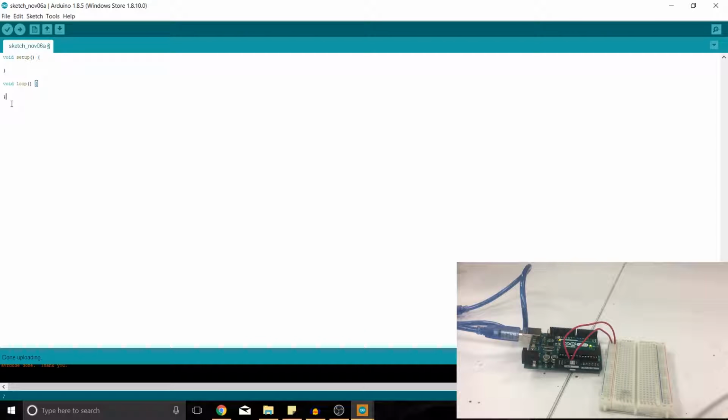And you can already see two things here in my screen. One says void setup and the other one says void loop. So they have pretty resemble names. So void setup, what you place in between these curly braces is going to be run only once at the beginning of your program. And void loop, it's going to be constantly running over and over again. So it's a loop. So what you do in setup is you place code that you want the Arduino to only run once, which is setup code. And here you place basically all your logic.